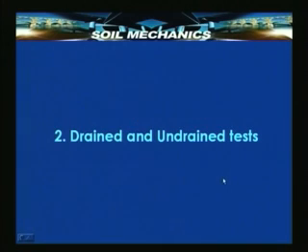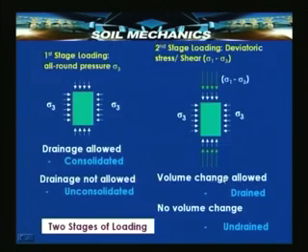Now, let us go to drained and undrained tests. Let us take the basic scheme which we used last time to understand the importance of drainage. Here is a typical triaxial test specimen. It is subjected to 2 stages of loading, as we know in the conventional triaxial test. I must mention here at this point of time, there are several different types of triaxial tests. The one which we normally use is the one which is called the CTC, or the conventional triaxial compression test.